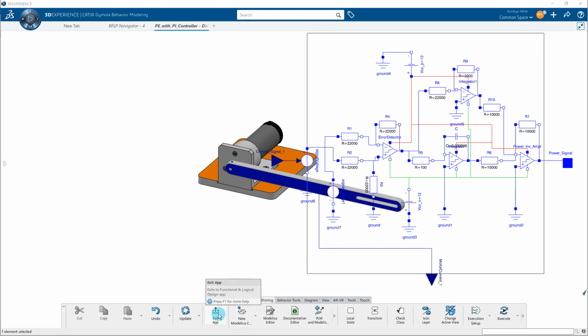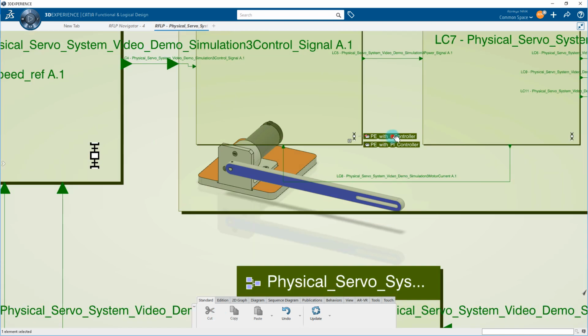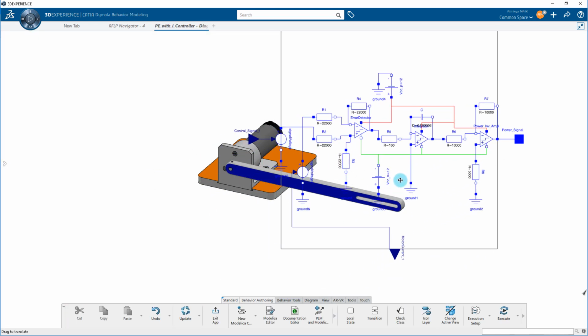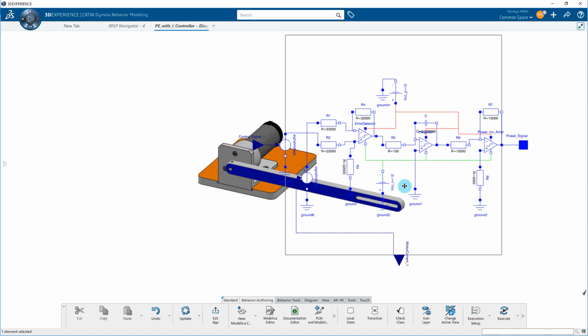Although the main objective of power electronics is to provide enough power to the DC motor, it is also possible to include the inner control loop, the electrical current loop, for the servo system. The next behavior shows a reduced version of the previous controller. The only difference is that here we are using only an integral controller, I, instead of a PI. We can use only an integral, I, controller because in this control loop we are only interested in reducing the steady-state error.